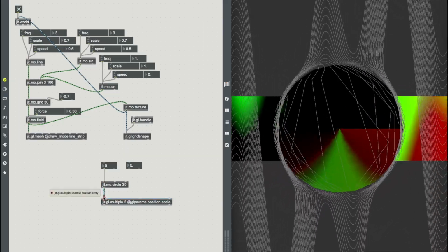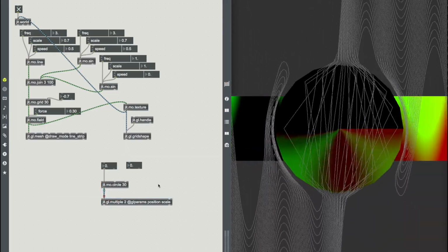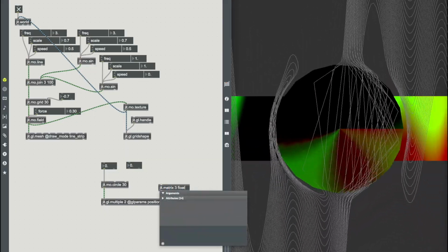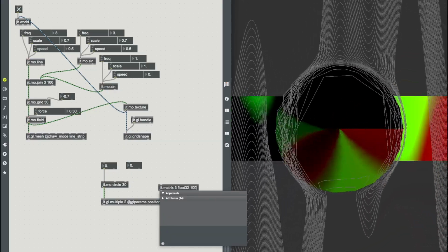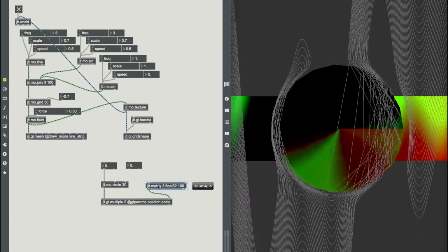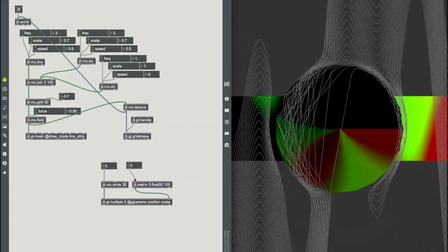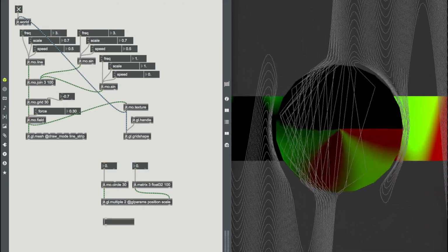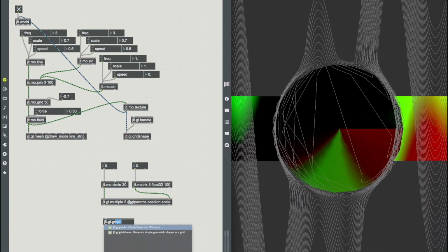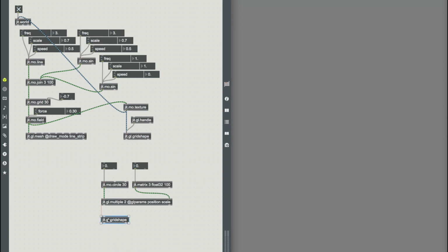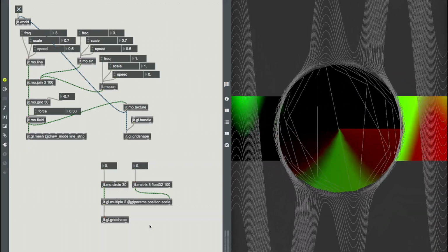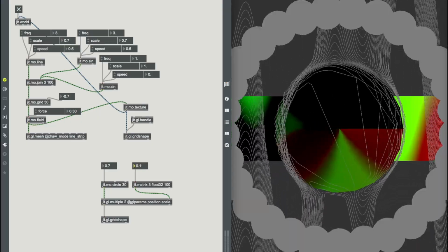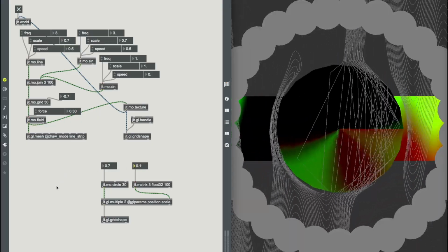Make a jit.matrix 3-plane object, float32 and a dimension of 100, and connect that to the right inlet of our gl.multiple. Connect the other floating point number to the jit.matrix. Now make a jit.gl.gridshape and connect the output of the gl.multiple to the inlet of the gridshape. Make the first number of our floating point number box 0.7 and the second number box 0.1. Now you should see a circle of 30 spheres.